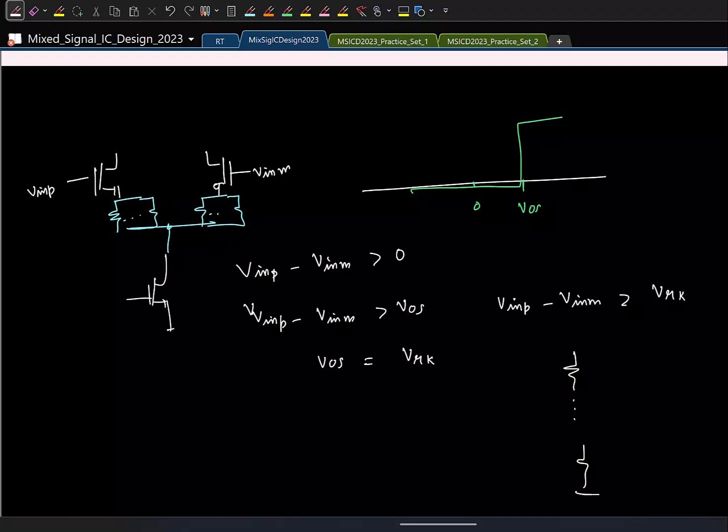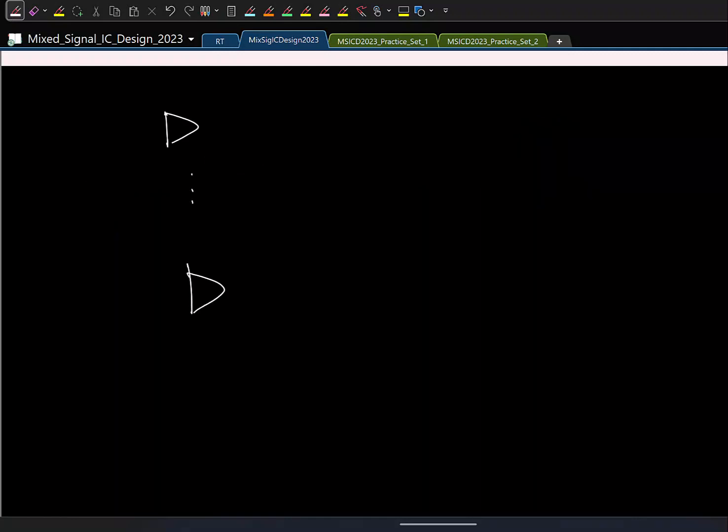Second, you don't have to subtract the reference voltage from the input, because we are directly applying the input here. The offset itself is there, and that itself is getting compared inherently. This is one thing that is commonly done. So what you have is a bunch of comparators, and only the input is applied, and inside you have a bunch of resistors.